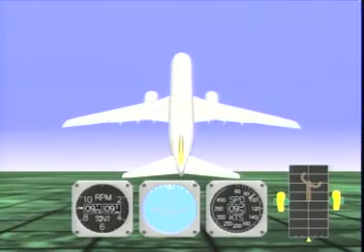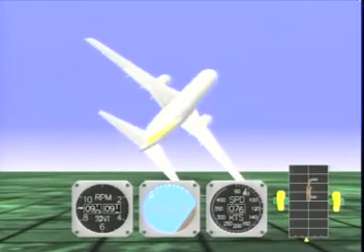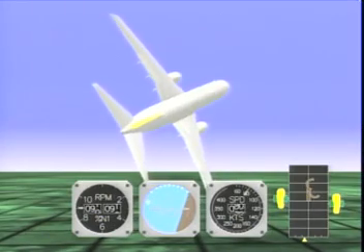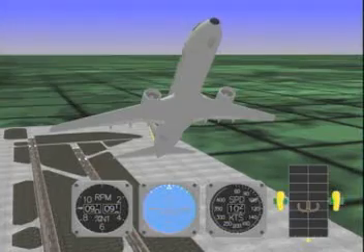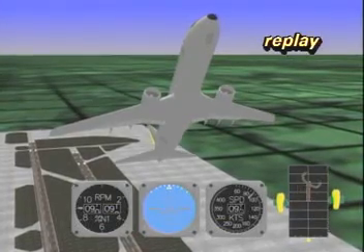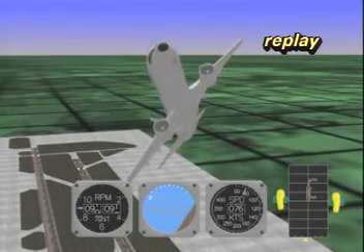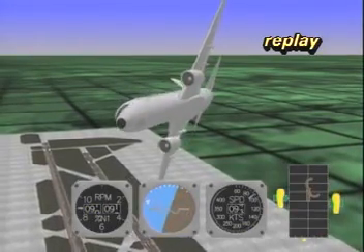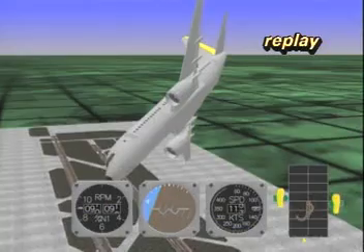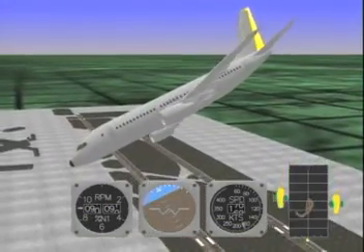If the control provided by the ailerons and spoilers is ineffective, rudder input may be required to induce a rolling maneuver for recovery. Only a small amount of rudder is needed. Too much rudder applied too quickly or held too long may result in loss of lateral and directional control. Because of the low energy condition, use caution when applying rudder.